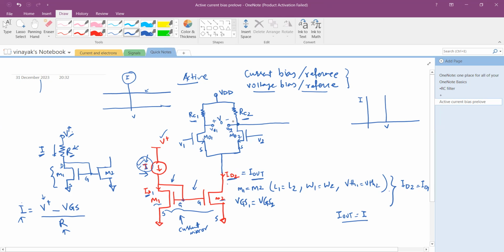And now let's say you have a single-ended output here that you use to connect to an output stage of the differential amplifier. So here is another differential amplifier. Again, you have another gain transistor, and then you need bias current for this branch also. So what you do, you connect the same, because now VGS for M1 and M2 are same. Use this generated VGS to apply to another transistor right here, and this is ground. This is how you have VGS here that biases another transistor, and that is your ID, whatever the name of the transistor. Let's say this is M5 and this is M6. So this will be ID6.